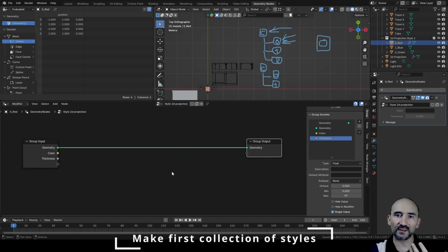I want to manipulate this object as if it was a single object and not a group of vertices. So I want to convert this plane into a single instance and save the color and thickness inside this single instance. And in this way, I can have in this output a unique object, an entire unique object as an instance and not a mesh.